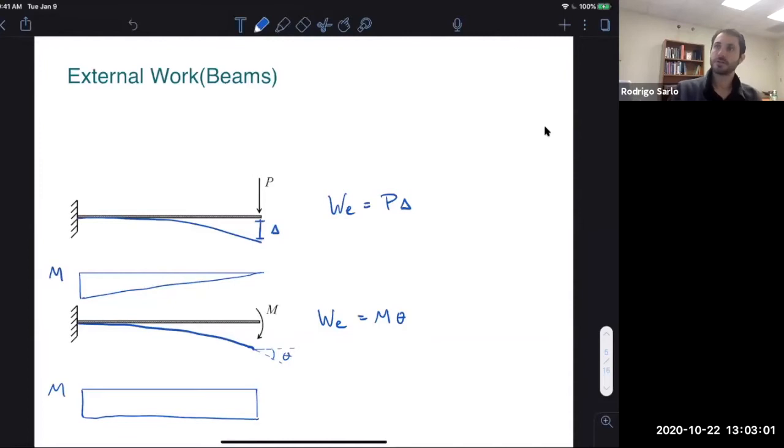Okay, so Jeff has another very good question. So is this a simpler way of solving for deflection as opposed to finding the deflection equation from derivatives, at least for a moment? In a way, yes, right? So principle of virtual work is a way to solve for deflections in a little bit more direct way.